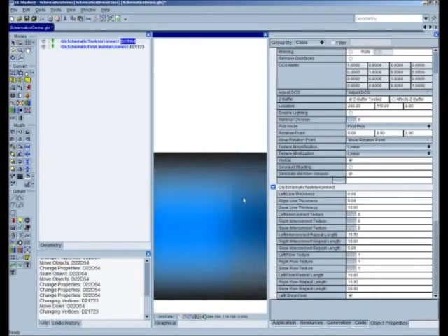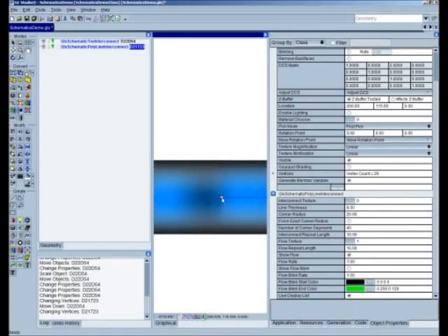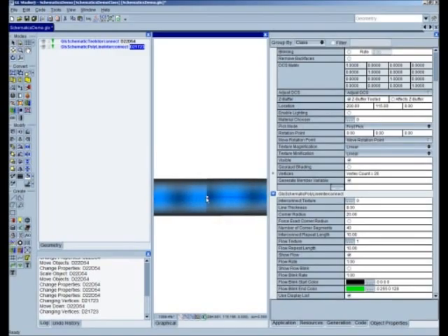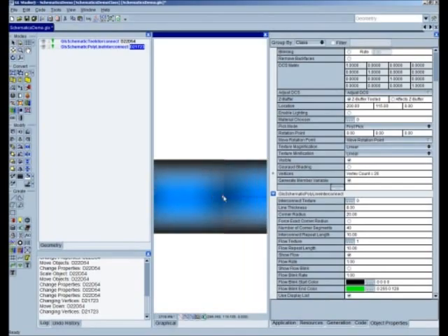We'll keep tinkering with that for just a couple minutes, but that is how you would do it. The important thing to note here is that the end of one texture should begin where the other one ends. If your Polyline Interconnect is significantly away from one to the other, you can see a lot more of a divide between one side and the other. We see it ending here, and then a significant distance later it begins on the other side. So the trick is to get it lined up as closely as you can. Once it lines up correctly, the break you see will start to go away.